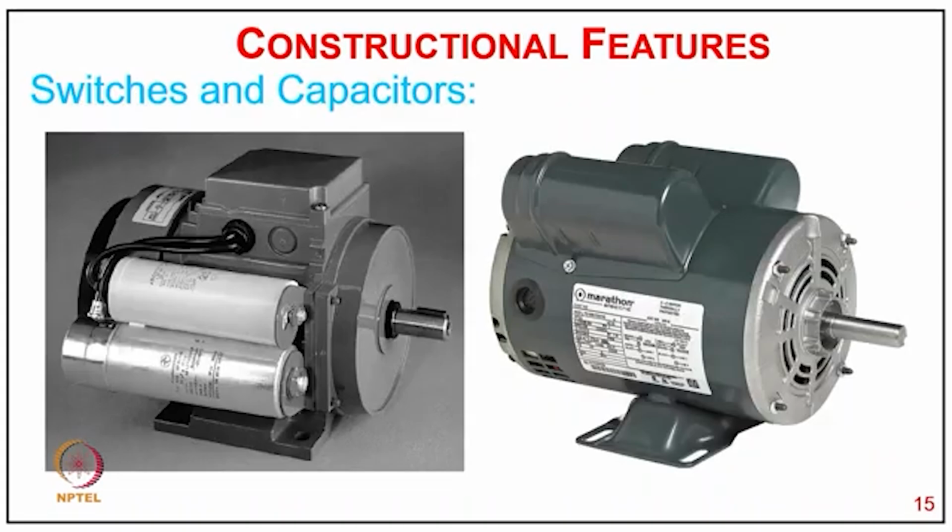Then you can see in the figure that you have two capacitors. One AC electrolytic capacitor is for starting, cut out by the centrifugal switch, and the other capacitor remains in the winding for high rating motors, so that it runs very close to a perfectly balanced two-phase motor with the phase shifting capacitor in the auxiliary winding. There are many concepts on having two currents in quadrature to create the two-phase field in this motor, which really gives a rotating magnetic field as close as possible to balanced operation.